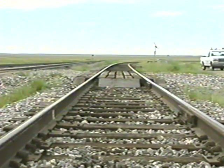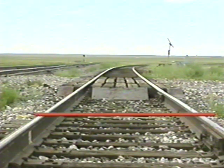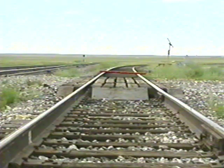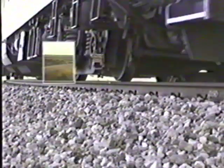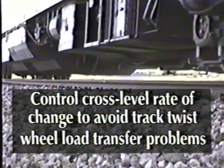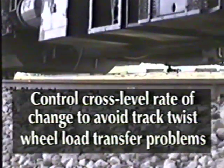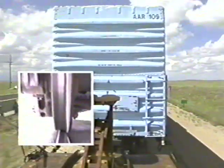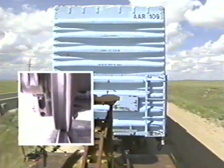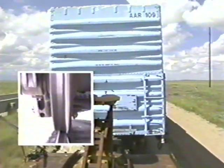Track twist is usually associated with curved spirals. However, the track will twist in any areas where there is a change in cross level. Curved yard tracks and turnouts are areas that often exhibit excessive track twist. The rate of change in track cross level should be controlled to avoid problems with wheel load transfer associated with track twist. Finally, wheel load transfer can be caused by dynamic roll, which is a side-to-side rolling motion of a